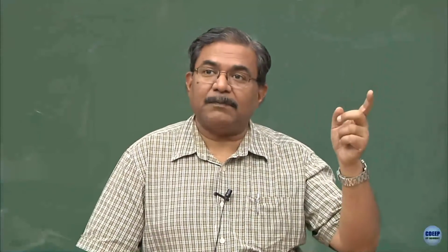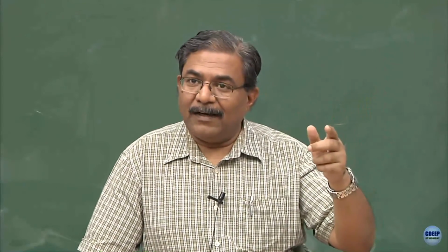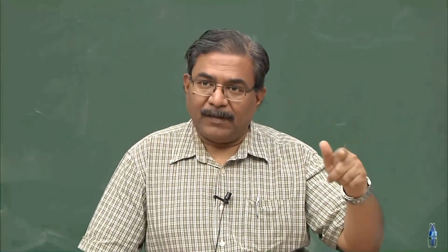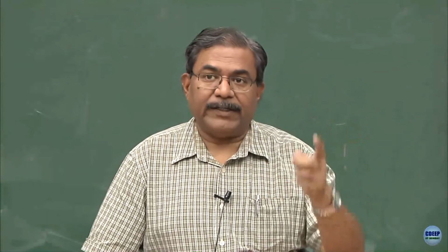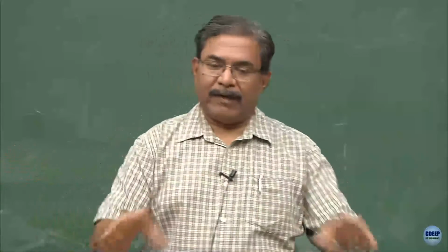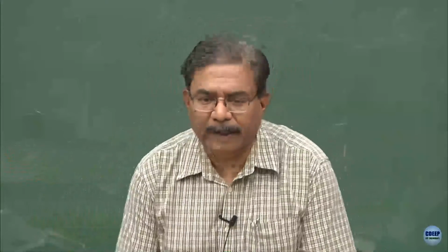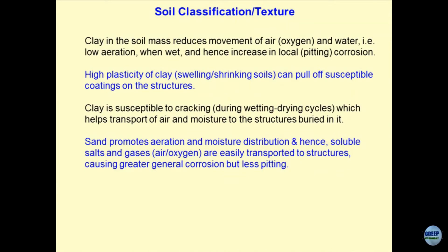Apart from the geotechnical aspects where we have said clays cannot be compacted, if I use clays in the backfill, tension cracks will develop, you agree? And then the chances are that the entire system will consolidate after some time. So, this is a lot of discussion between fine grained material and coarse grained material, but coming to the point, sands would promote aeration and moisture distribution properly, and hence the corrosion potential of the sands is going to be less. So, it is a pure research area.